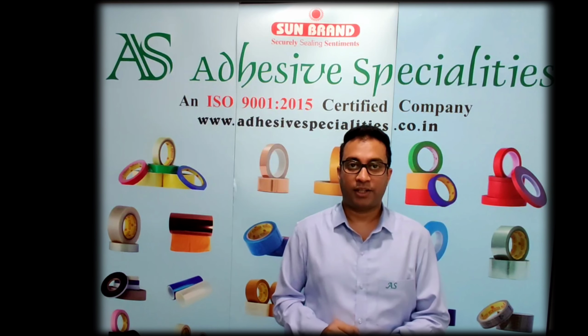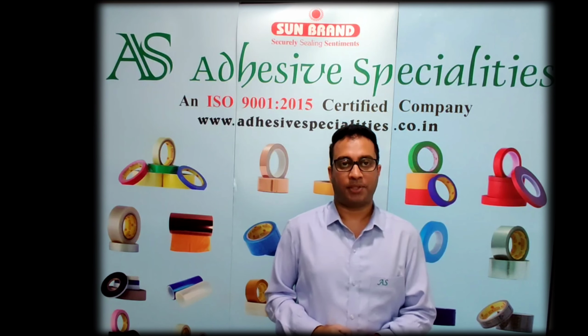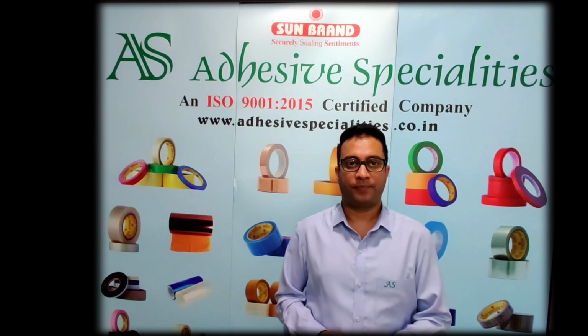What are the basic properties that control the performance of PSA tapes? There are many factors or specifications which are particular for electrical tapes. The properties of the carrier and adhesive control the performance of an electrical tape. The carrier properties: thermal class, dielectric strength, elongation, absorption, abrasion, tear resistance, and thickness. The adhesive properties: adhesion, chemical compatibility, color, and thickness.